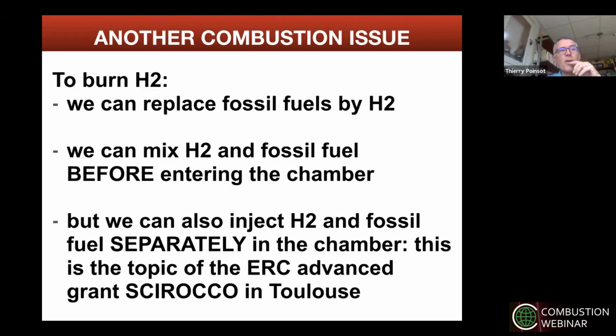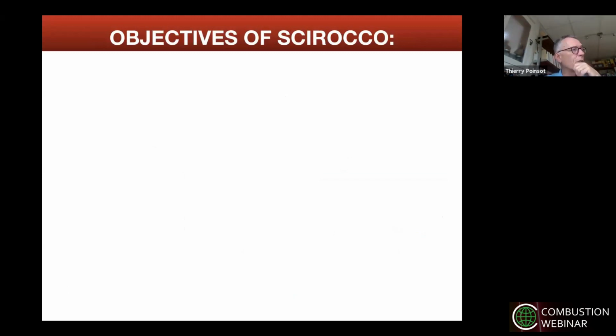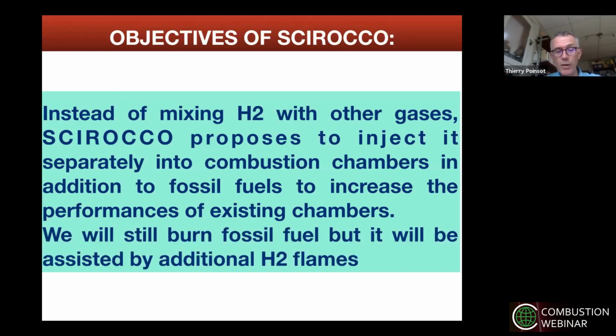And this is exactly the topic of this big ERC project that we are leading at the moment in Toulouse, which is called CERFACS. In this project, we actually study how you can use H2 to burn fossil fuels more efficiently. So here, the objectives of CERFACS are listed. Instead of mixing H2 with other gases before combustion, we propose to inject it separately into the combustion chamber in addition to another fossil fuel and to use that to actuate the chamber. We will still burn the fossil fuel, but it will be assisted by additional H2 flames.